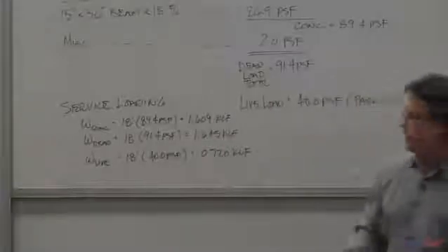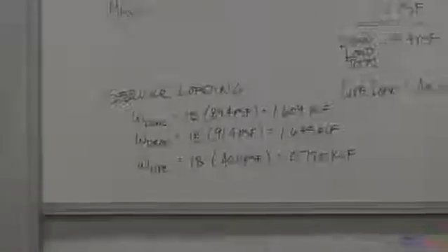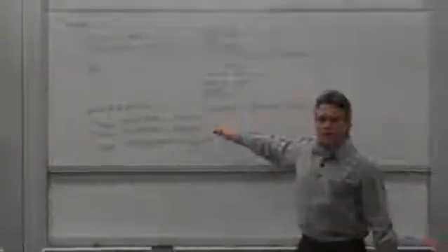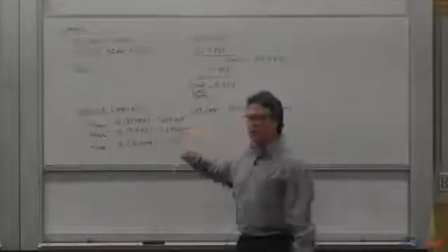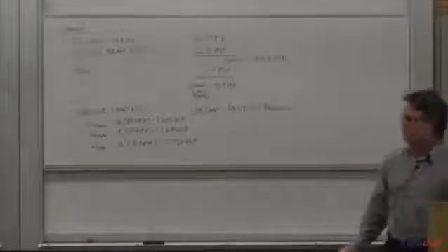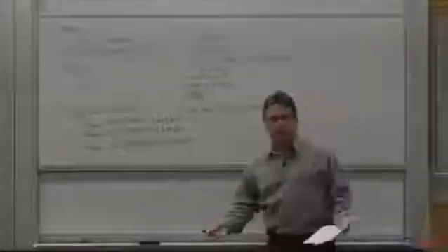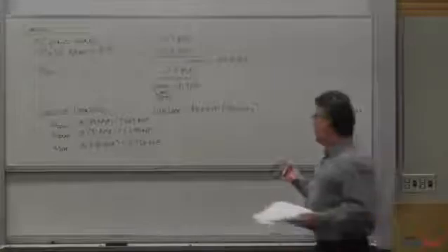Okay, service loading, unfactored. What do you think we're going to use the service loading for? Stresses. That's right. The concrete only, and I want you to calculate this because we're going to estimate the pre-stressing based on just concrete weight. It's the only thing in most of the buildings that you're going to design that will always be there guaranteed. We only pre-stress and balance loads that are always there 100% of the time. That's our philosophy.